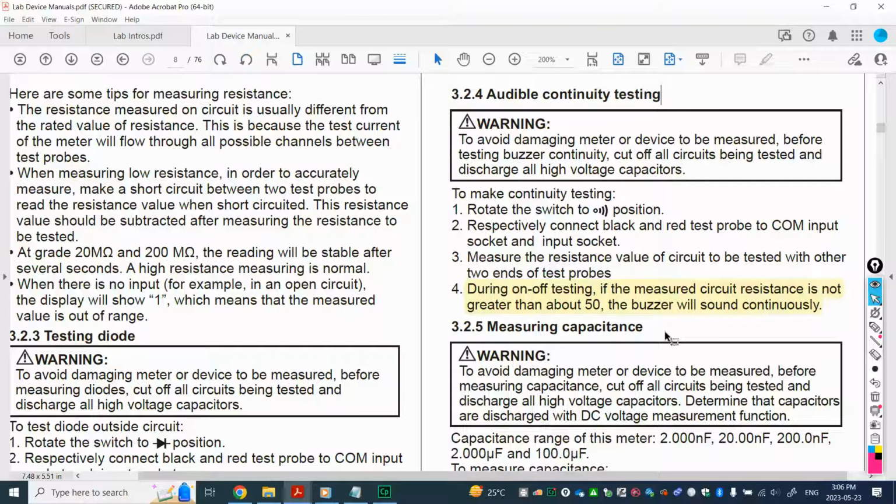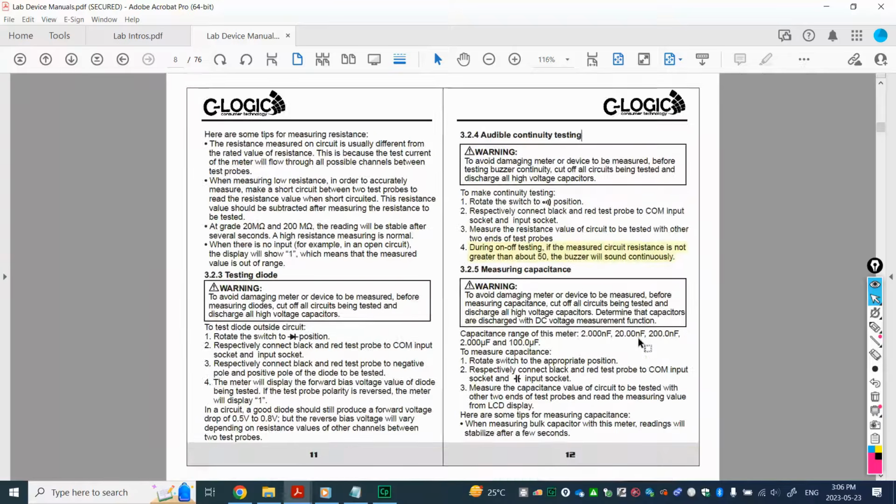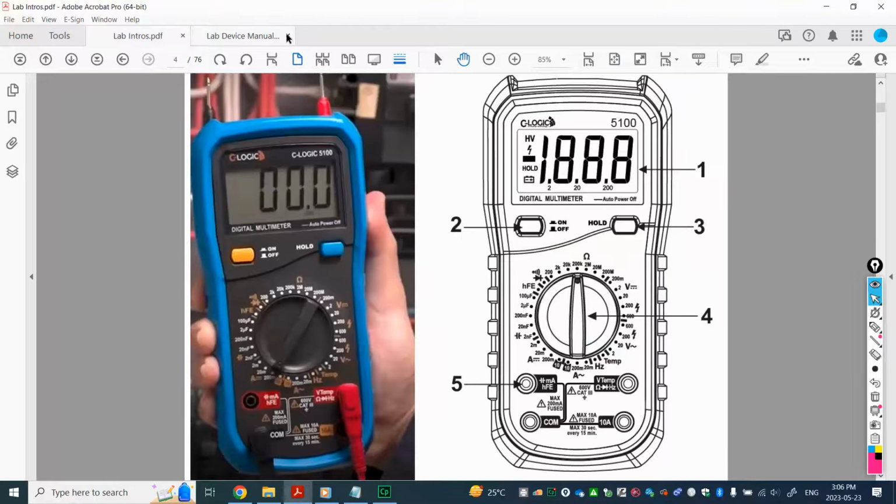If you find that confusing, you can also switch to the resistance reading, and also look for less than 50 ohms. That means if something is just a little bit over 50, for example only 55 ohms, not a big difference from 50, then if you use the continuity testing, you won't be able to hear the beeping sound. But if you measure the resistance, you will see that it's very low resistance. So that's something I actually want to talk about, all right?